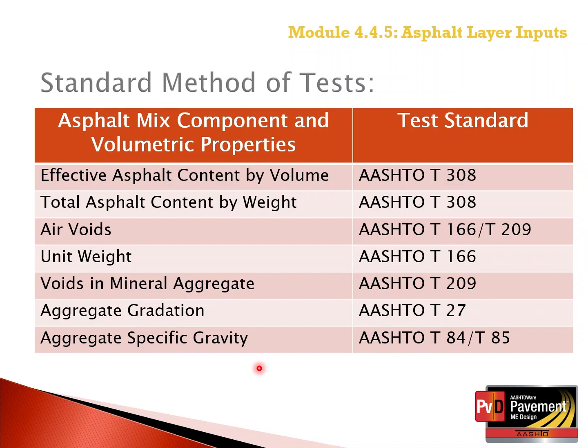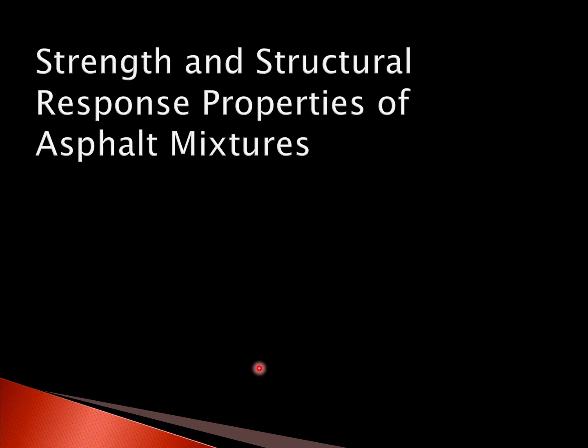The asphalt mixture component volumetric property test procedures are listed in this table. Remember, the volumetric property values entered in the PMED software should represent the values at the time of construction. They are not the mixture design values. This section focuses on the strength and structural response properties for the asphalt layer.